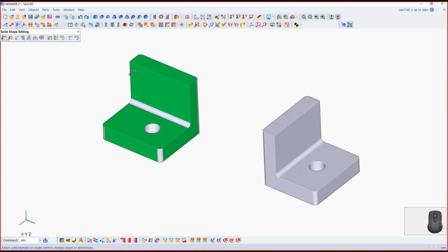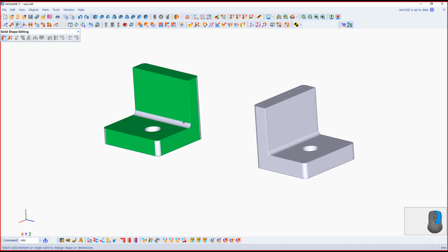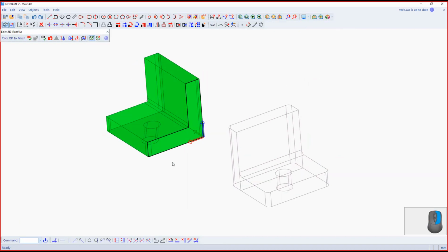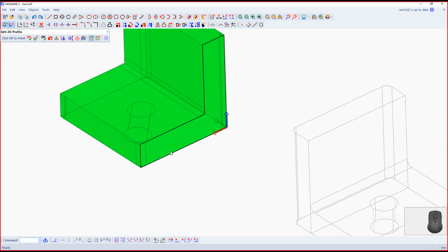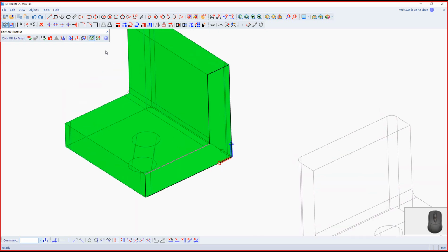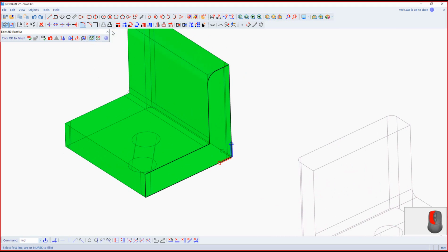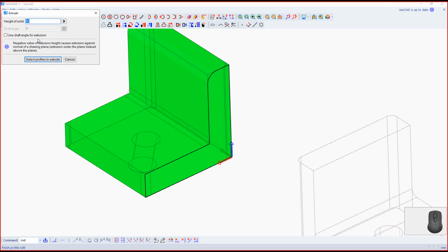And this is interesting because the program identifies the different things I have in my drawing. So this solid here was created coming from the 2D, so you can see that it turns the profile again so that I can change the profile. For example, if I create a fillet, something like this, and say, okay, finish profile edition, I will maintain all the parameters.